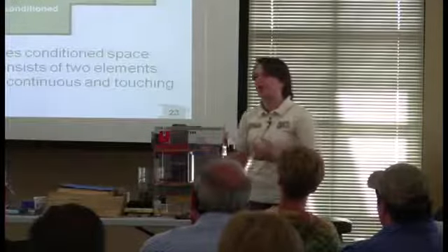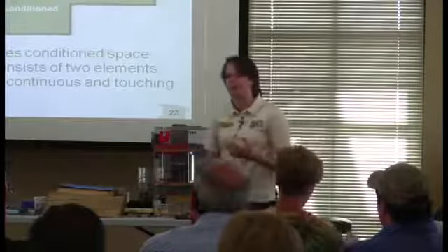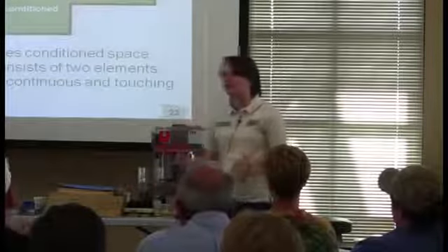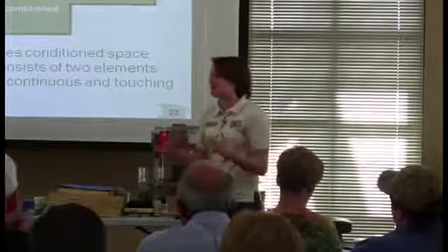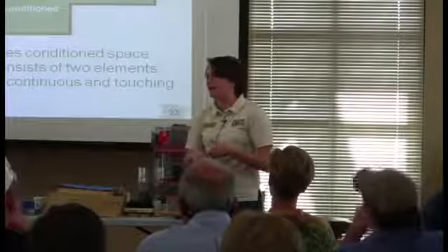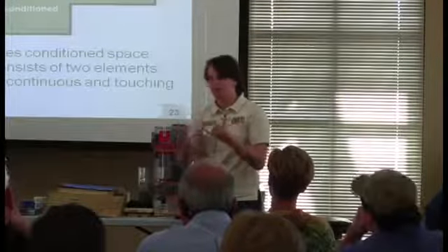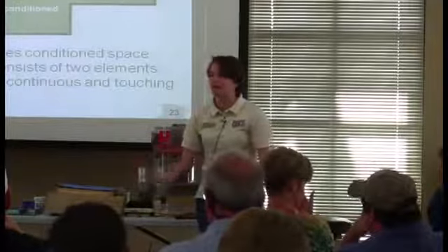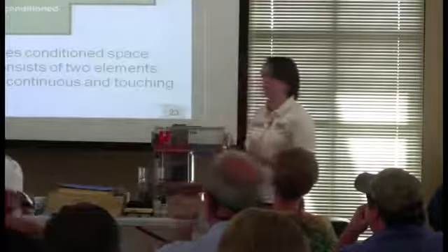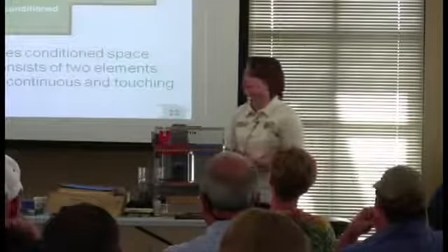And where you define your beer cooler, or your building thermal envelope, for every house it's probably different. There are no wrong building envelopes unless you don't have that air barrier and insulation in full contact and continuous. When you're designing your house, you also want to make sure you've properly sized and installed your heating and cooling system. That doesn't just mean that you have the right furnace or the right heat pump or the right air conditioner or the right air handler, but it also means I have the right ducts, the right duct size to actually distribute all this air that we've cooled or heated, and it's actually getting to the comfort of the occupants. Really use ACCA Manual J, Manual S, Manual D.